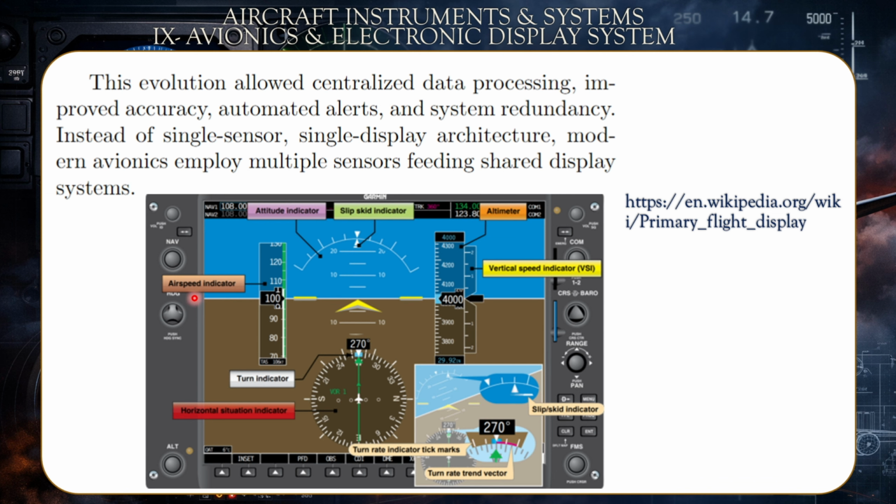Okay. And to the left, you have the ASI or airspeed indicator. Also here, the turn coordinator, and the HSI, horizontal situation indicator, which is the compass commonly known. Okay. Slip and skid indicator here, as you've seen. Okay. Turn rate in degrees. So yeah, this is the turn rate here via the turn indicator. So all of these instruments are integrated in one display. Okay? Of course, they are not simply one instrument. No, the reading, the display is integrated on one computerized screen.